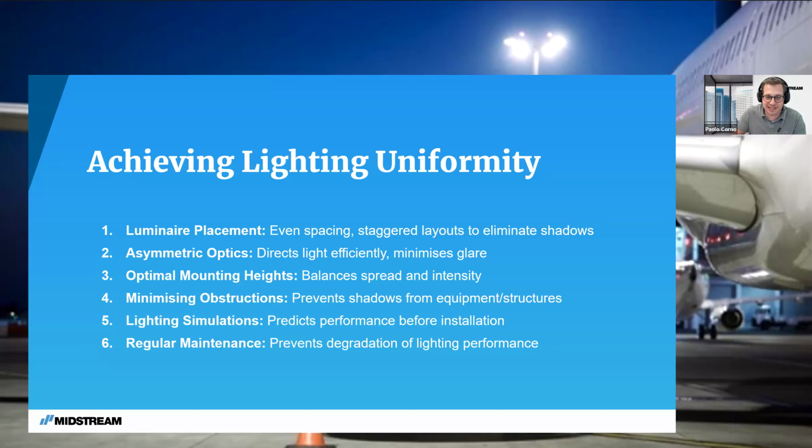And this is the only way to ensure that once something is installed, it's gonna look good, perform well, and be functional, is to have done your homework while doing the lighting simulation, account for whatever extra units you might need, because the area has a lot of obstructions, and instead of trying to save 3 luminaires on a major international hub, you install those, then it's going to be a good result on the field.